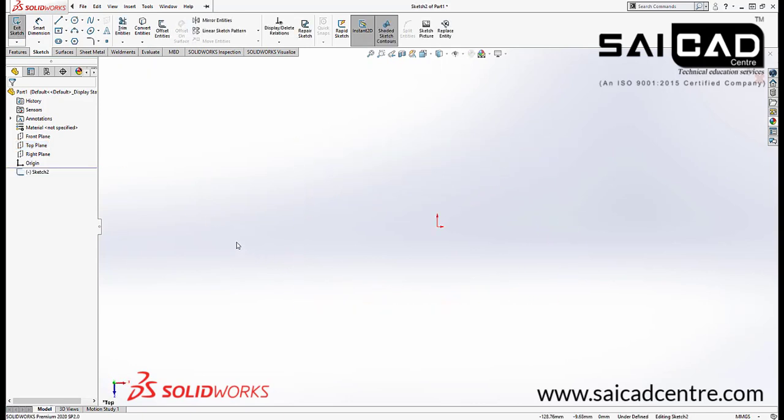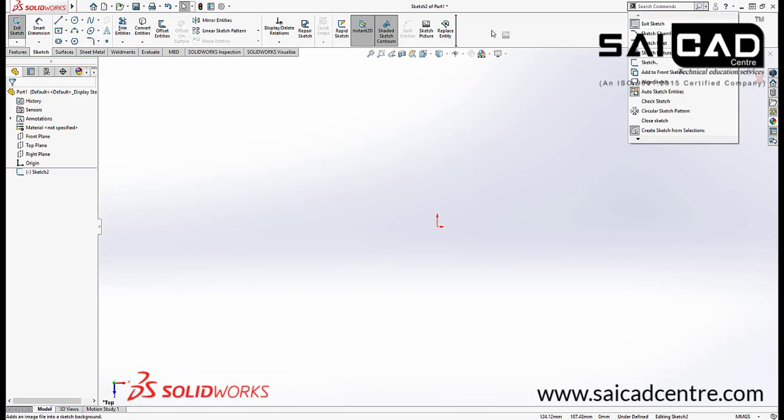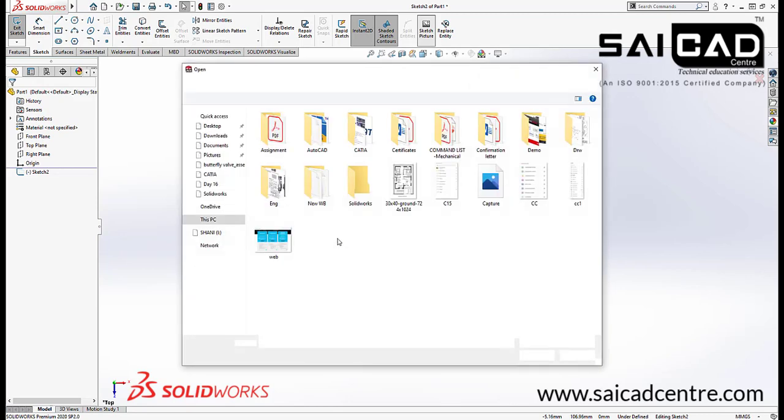In order to insert your image, you have to search here for the command that will be the sketch picture. I have already searched this command and I have already placed it here. You can just search it from here like sketch picture and drag this right here. So I have already placed it here, so I'm going to escape out and select the command.